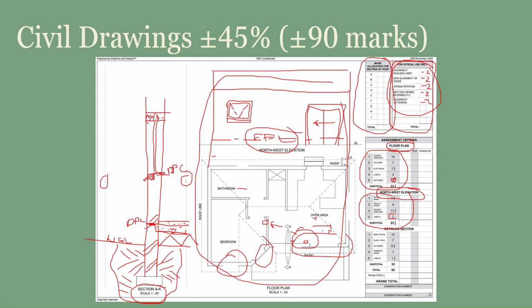When it comes to the roof, this is the part that most students struggle with. So you will have an extension there, then you're going to have a wall plate. A wall plate hatching is opposite corners. It's like an X in that block. And then you're going to have a truss that rests on that wall plate.